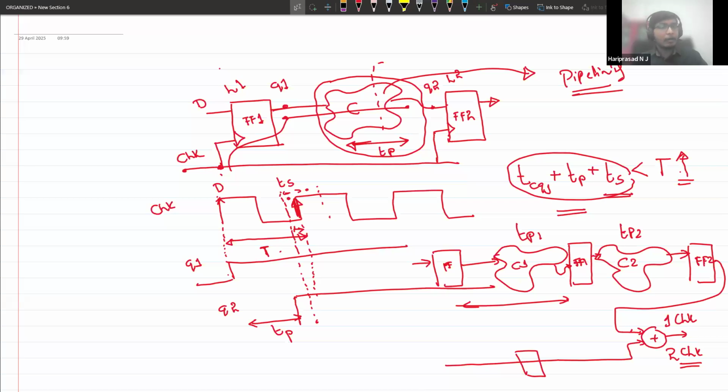So this is the methodology for how you can solve it. But there are actually many misunderstandings with respect to FPGA. Whenever I ask people how to solve setup or hold violations in the FPGA, the usual answer is, I will put a false path constraint, I'm going to put some multi-cycle path constraint, or I'm going to put some delay constraint. So constraints are not solving the violation.